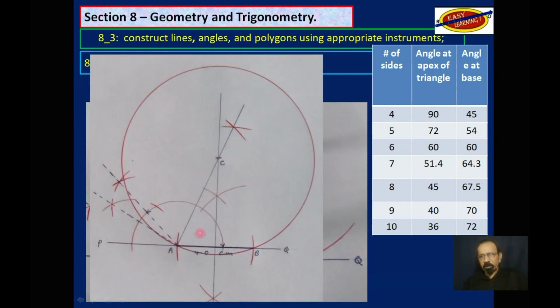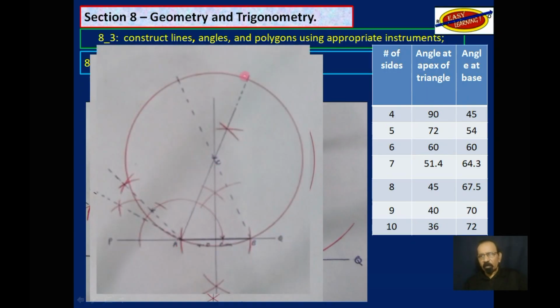So we get this circle, and now we will take our compass, open it to AB, which is 4.0 centimeters, and make marks on this circle. However, before we do that, we will extend this side here, and coming from A, we will extend that through to that point as a precaution, like that.